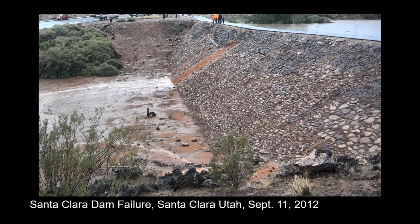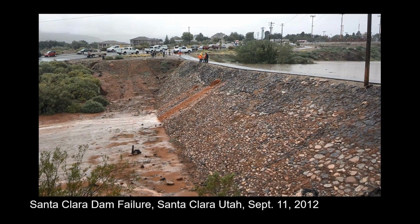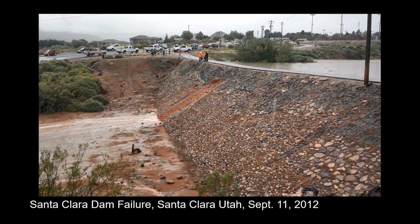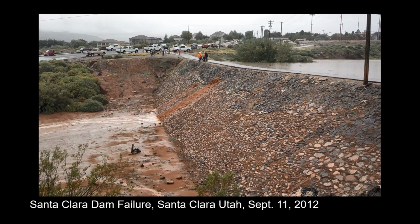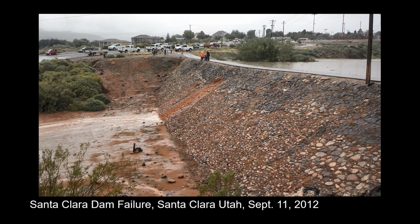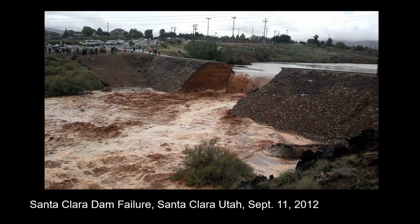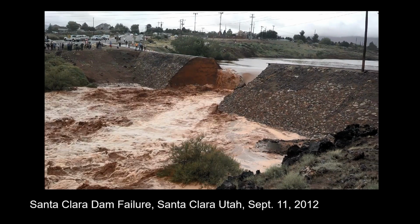This is a 90-year-old dam. And as they were experiencing this record flood event, they were actually observing burrowing animals exiting the dam at different locations. And you can see here is where there was a concentrated flow. As the reservoir came up near the crest of the dam, the flow broke through. We had a concentrated seep, and that eventually led to a complete breaching of the dam.